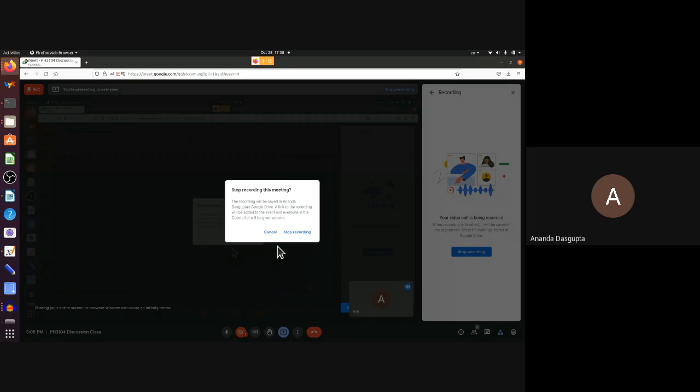But because you're interested only in the fluctuation around the bias point, you don't worry about this addition that you should do at the end for the superposition principle. You don't bother doing that simply because you're interested in the variation anyway. Right? So you could add the DC back and say, okay, this is the voltage, but you're not interested in the DC part. You're interested in the signal there. So you don't bother adding back the DC part. That's all there is to it.